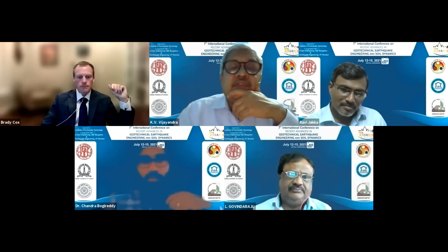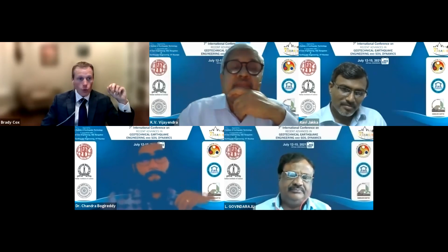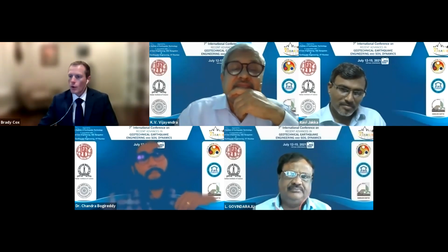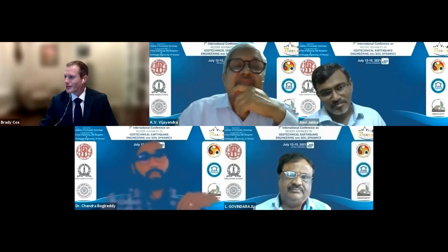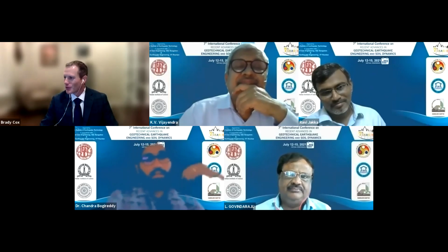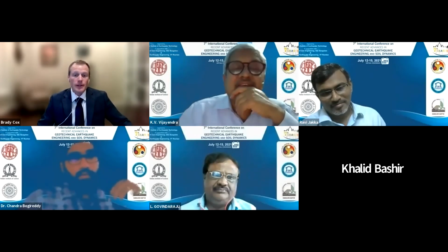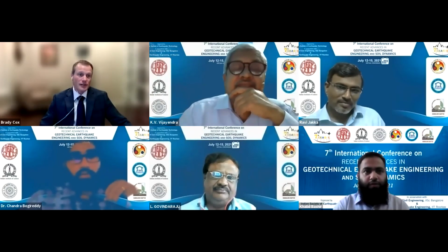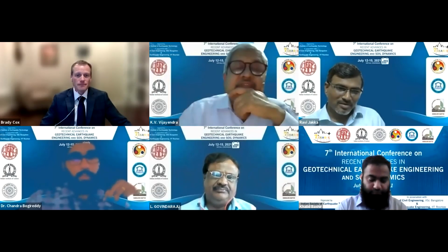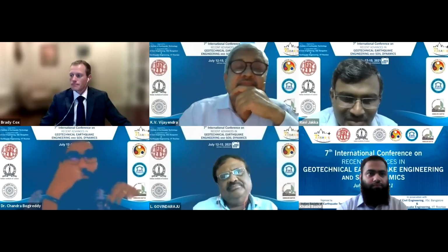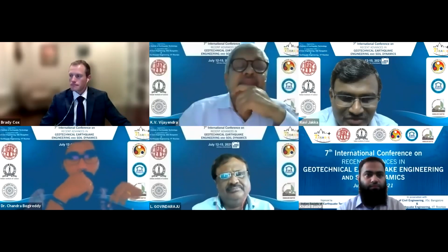What was the fourth or fifth mode frequency of the Treasure Island downhole array? The fourth mode frequency? Yeah. It's less than 10 hertz. So I'll quickly go to those results and tell you real quick. The fourth mode frequency at Treasure Island is only about 5 hertz. So it's a pretty soft site. It's a really soft site. Filtering has not affected those modes. That's correct. Yeah, just one follow-up question.